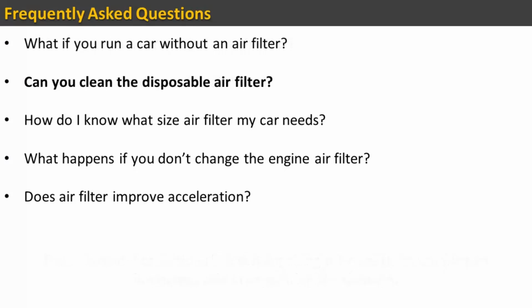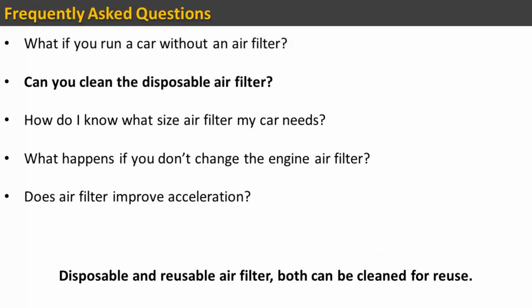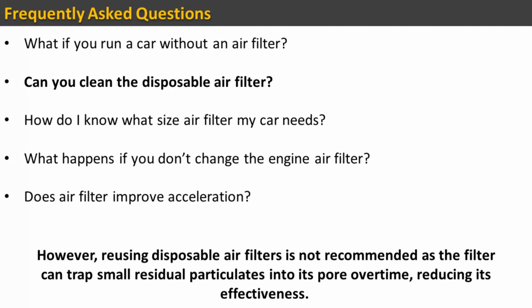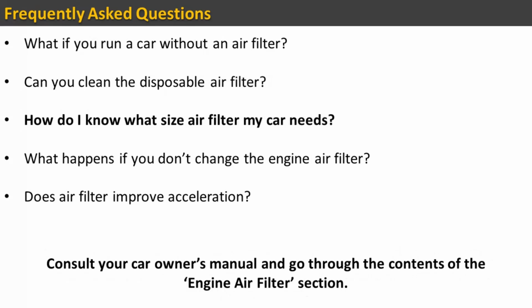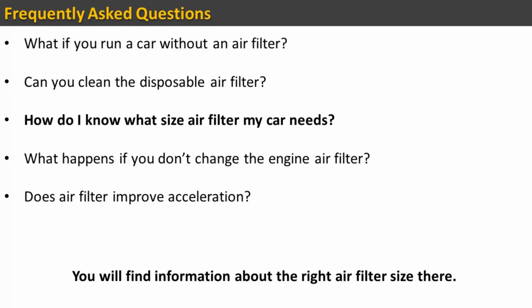Can you clean the disposable air filter? Disposable and reusable air filters both can be cleaned for reuse. However, reusing disposable air filters is not recommended as the filter can trap small residual particulates in its pores over time, reducing its effectiveness. How do I know what size air filter my car needs? Consult your car owner's manual and go through the contents of the engine air filter section. You will find information about the right air filter size there.